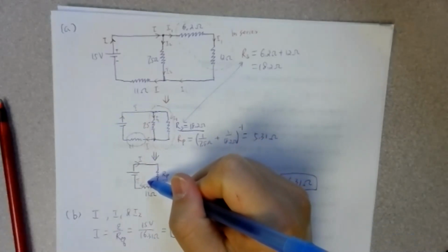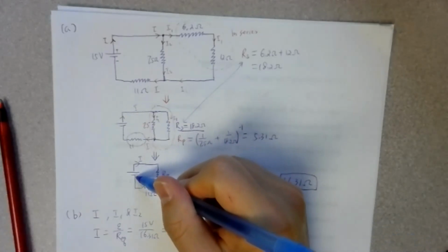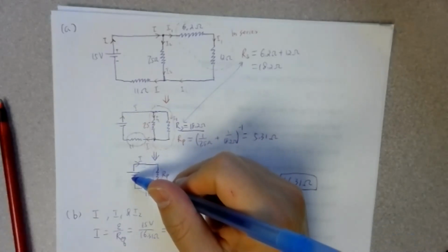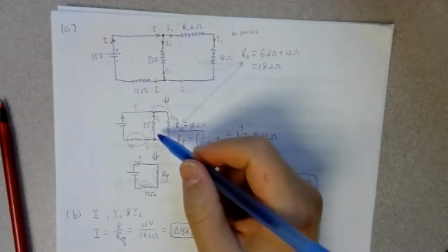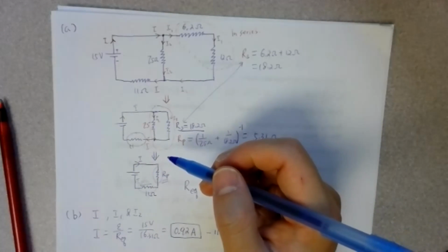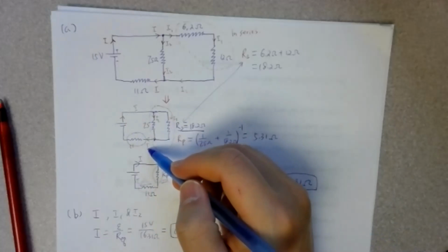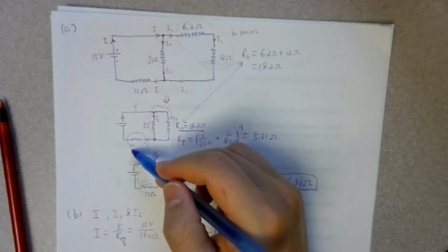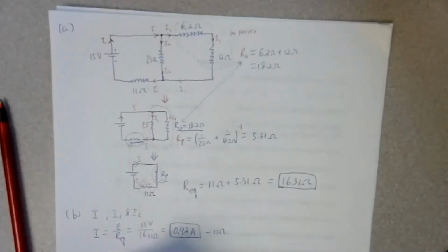That's how you can see it, because this one is in series with that part. Or you can look at this one. The voltage on this plus the voltage on this should be equal to the voltage from your battery. It's similar, just replace these two with this equivalent. Then you can figure that out. So we have the overall voltage epsilon, we have the I here, and we have these ohms, so we can figure out the voltage across that one. So the voltage across the 11 ohms.